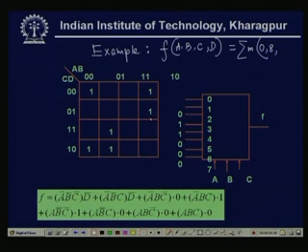For the second row, this is 1 0 0 1, this is 9. Third row, this is 0 1 1 1, 7. For the fourth row, it is 0 0 1 0, means 2, and this is 0 1 1 0, means 6. So, these 6 minterms are there. This is one combinational circuit I want to realize using a multiplexer.